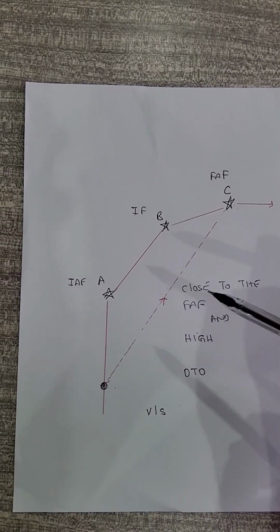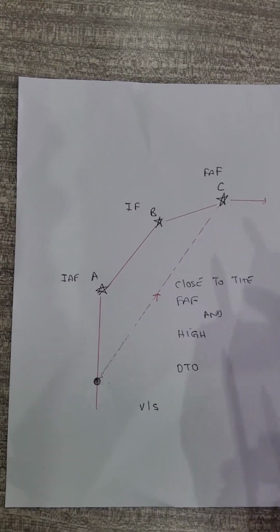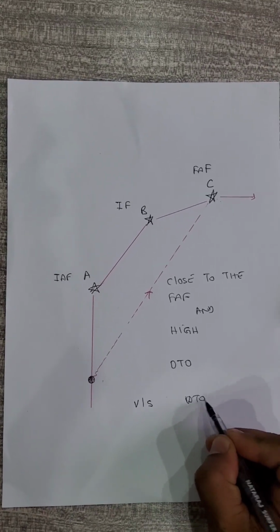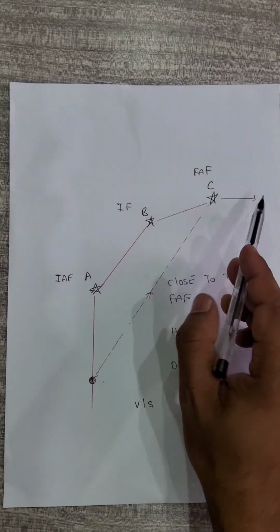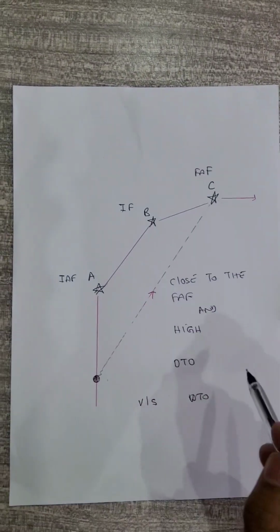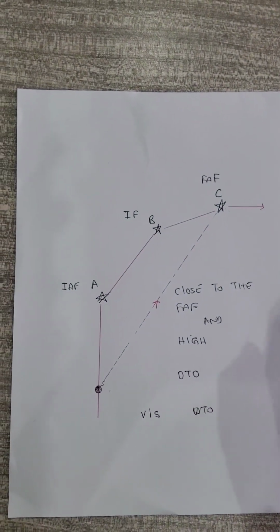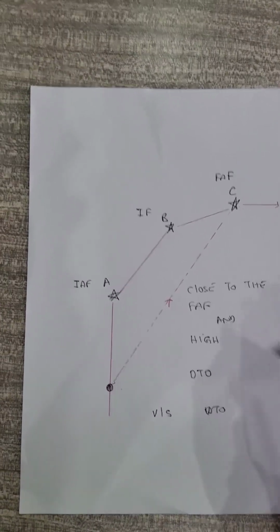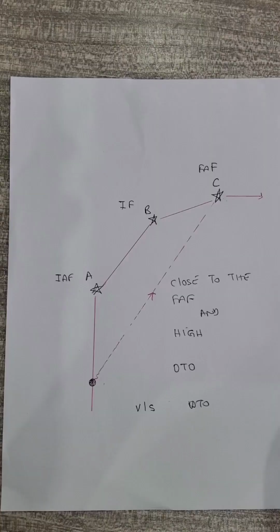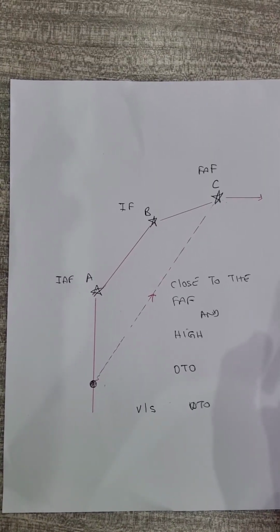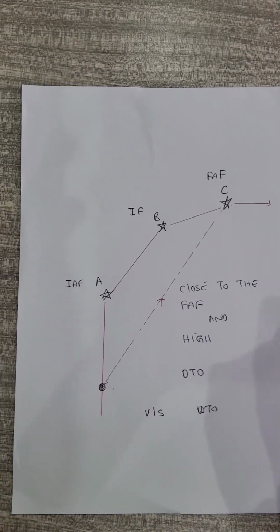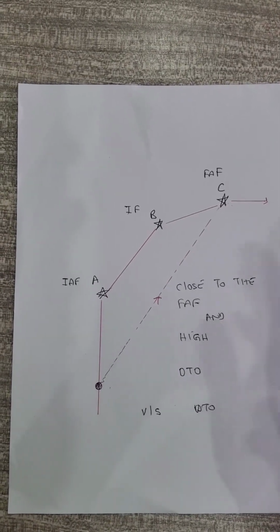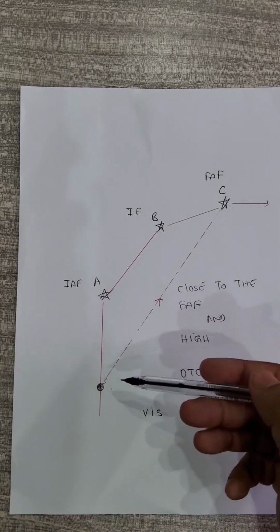Then we'll first of all do DTO to the fix. So we'll tell the aircraft let's go there, but for now it won't dive because the vertical speed has been locked to what it was initially with VNAV. So if VNAV was giving you a vertical speed of, let's say, 1300, at the moment you press vertical speed it's going to maintain 1300, unless you use a thumb wheel, which you shouldn't anyway unless there's a need to, depending on your calculation of the distance.